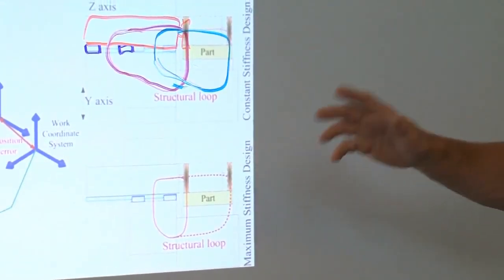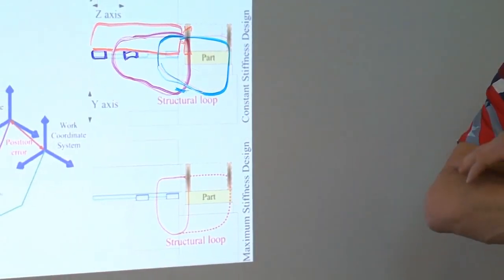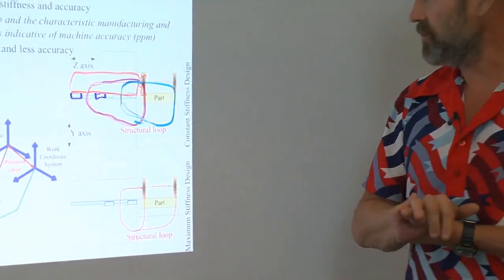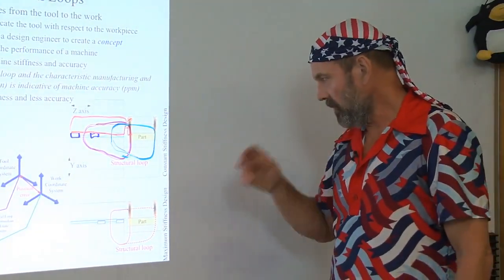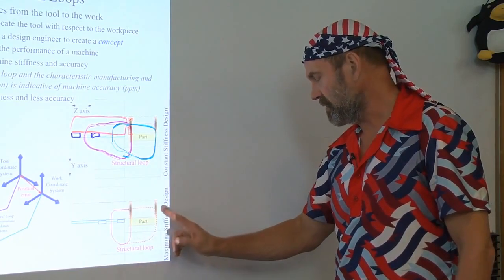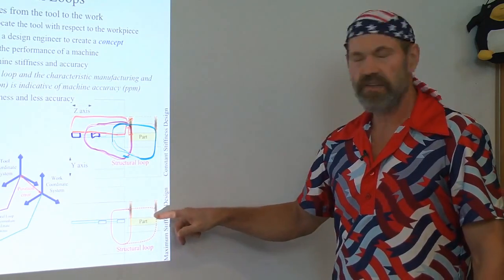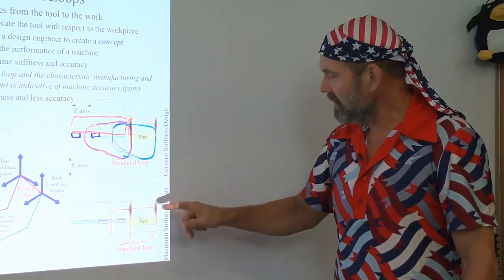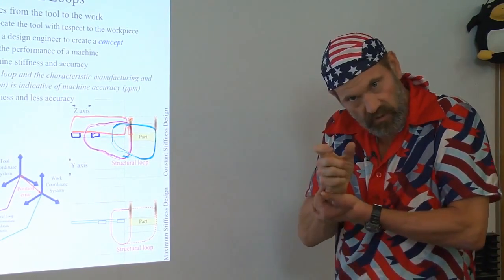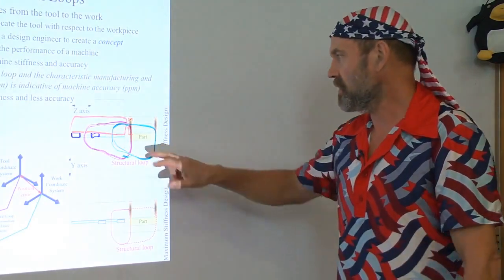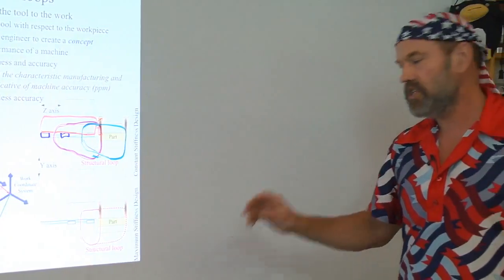That doesn't mean that this machine is better than this machine. It depends what you're using the machine for. This machine would make a better production machine where I have to rapidly produce large dies, for example. This, for example, is a better tool room machine where I can take the time to grind as the z-axis moves back and forth to what is called spark out, which means there are no forces on the tool anymore. And it also means I have a position in this machine where it's really super stiff for the highest of high precision grinding small, hard ceramic parts, which this upper machine would have more of a trouble dealing with. So it's all about what you want your machine to do.